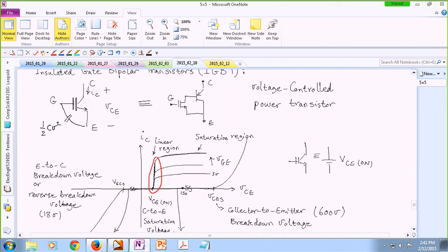And the gate driver has losses, and you're going to lose some energy over here. So you realize you're losing, for instance, a couple of watts just in the gate signal, basically. So the more the better, ideally, but at the same time, you're actually increasing the losses to the system. Any other questions?